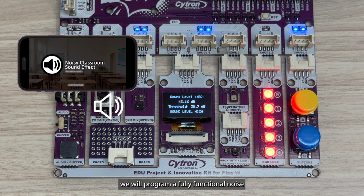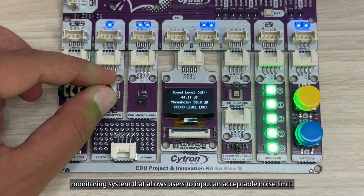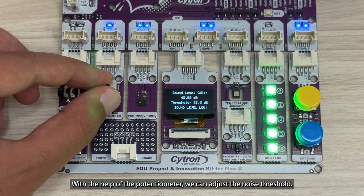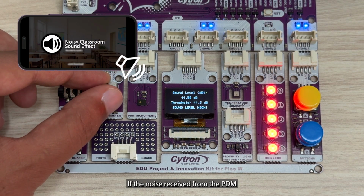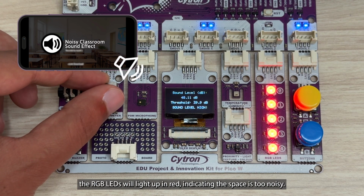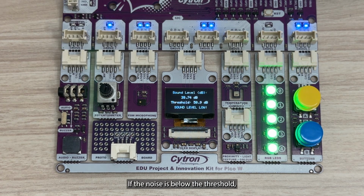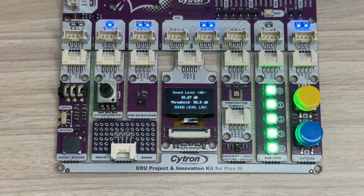In this video, we will program a fully functional noise monitoring system that allows users to input an acceptable noise limit. With the help of the potentiometer, we can adjust the noise threshold. If the noise received from the PDM microphone exceeds the threshold value, the RGB LEDs will light up in red, indicating the space is too noisy. If the noise is below the threshold, the RGB LEDs will light up in green, indicating a safe noise level.